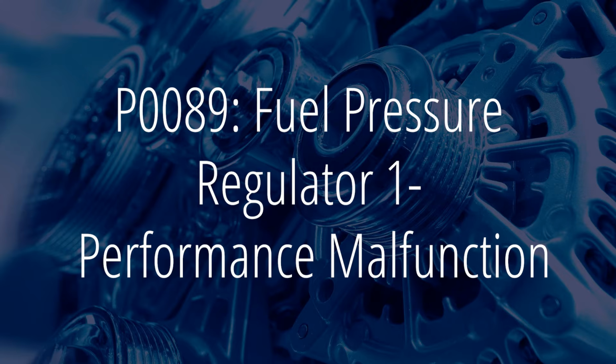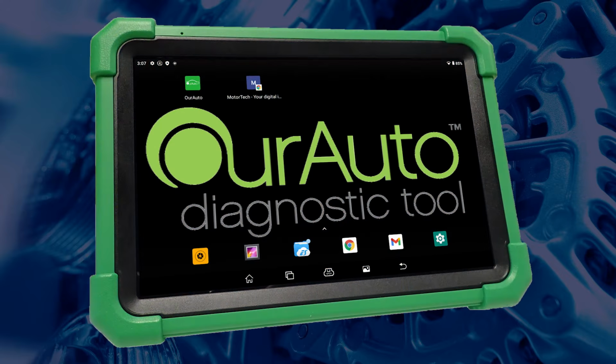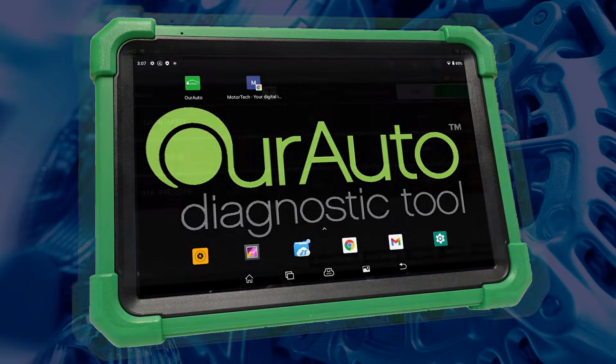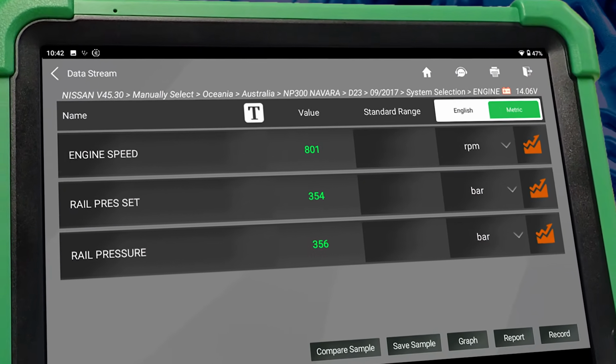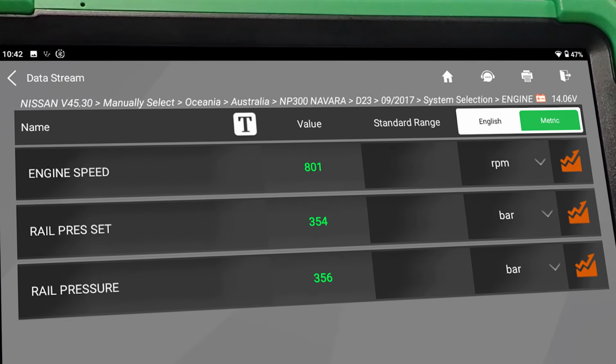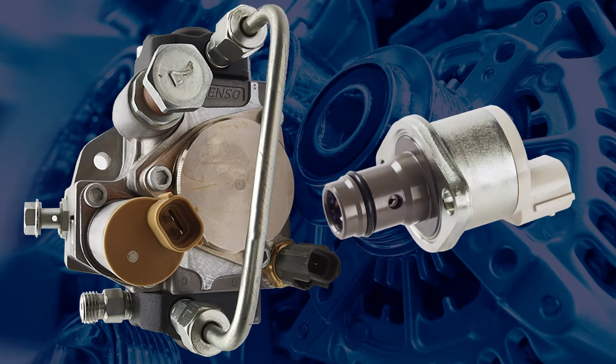A compatible diagnostic tool is essential, as it can allow you to check the actual and desired fuel pressure readings via the live data list. If they are higher, lower or fluctuating, this will give clues to your problem. A diagnostic tool should also allow you to complete many fuel component relearns, as these might be needed to be performed before this code will clear.